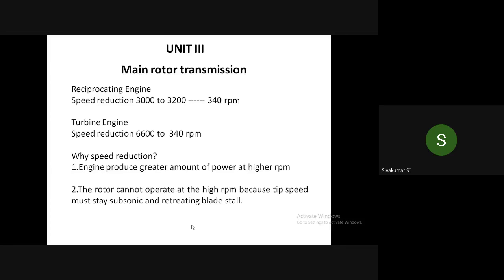Even compressor instability is there. Suppose you study turbojet and jet engines, high bypass engines and all. There is compressor instability because of stall, which makes the blades stall if you have a larger stalling angle. The stability of the airflow inside the compressor, which has an 18-stage axial flow compressor with stator and rotor, is lost, and with the instability of airflow inside the engine, there will be a flame out.